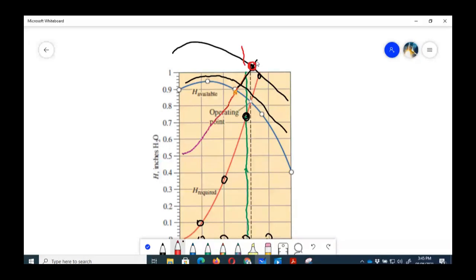In the industry, where you want to select a pump for a particular application, you do all these calculations, and you have to do multiple calculations, not one calculation as we showed here only for 600 cubic feet per minute. You have to do it for maybe at least 10, 20 values. So either you use some kind of program in C or Fortran or MATLAB, you can do anything you want, so that you can find a suitable pump for a particular application.